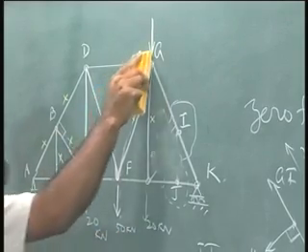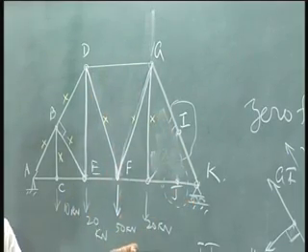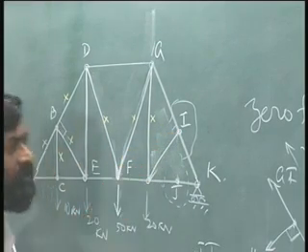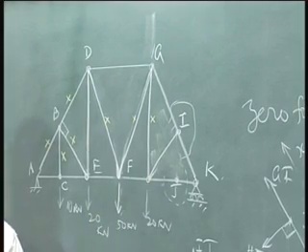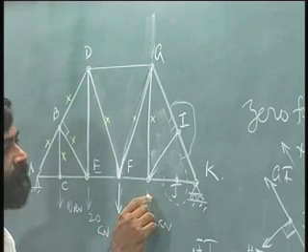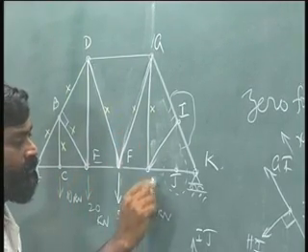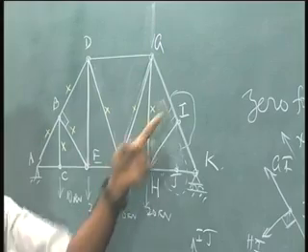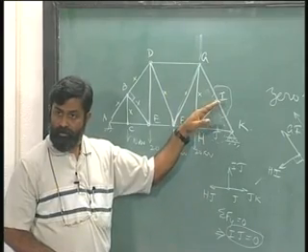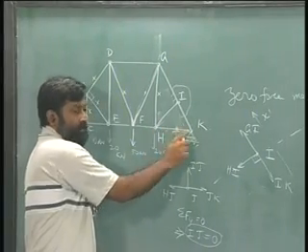If you analyze for the problem that is given already, you will find that this member is under compression and therefore likelihood of this buckling is more. So I would want to support it like this to a particular point, nearby point, and this particular member, this is joint A, B, C, D, E, F, G, H. HI member is primarily to support the member GK, okay. Similarly you will find that this is under compression, okay.